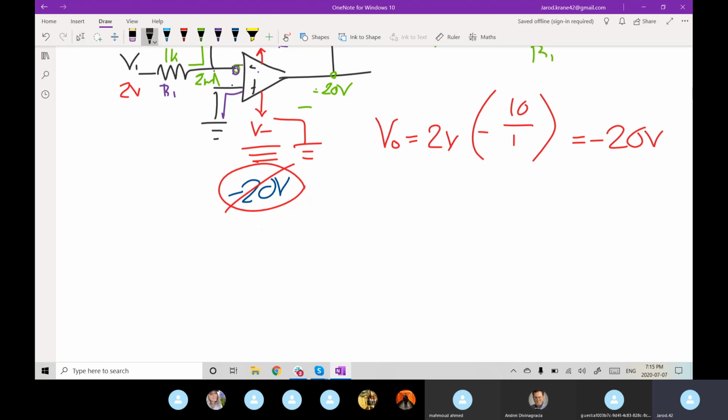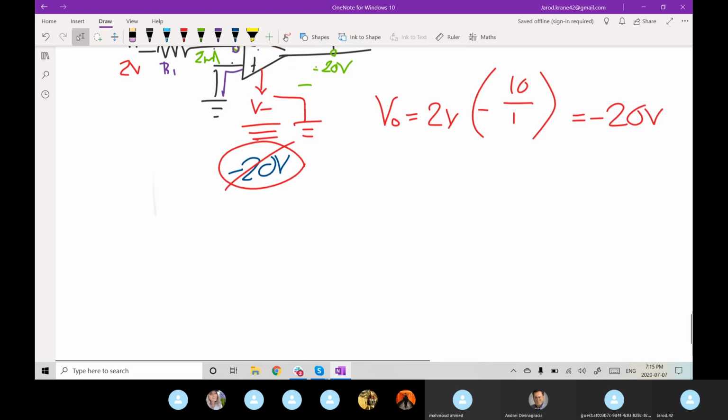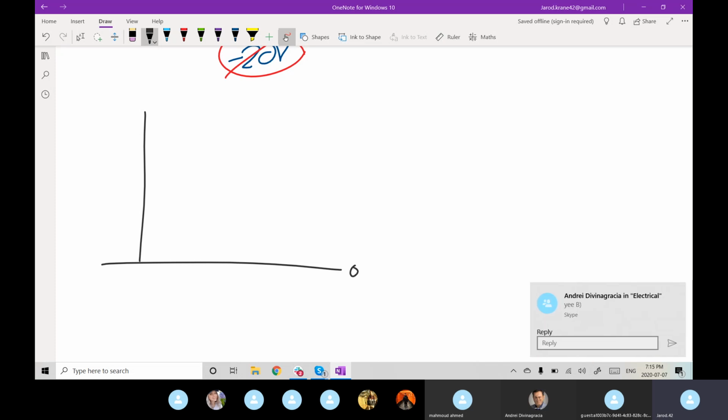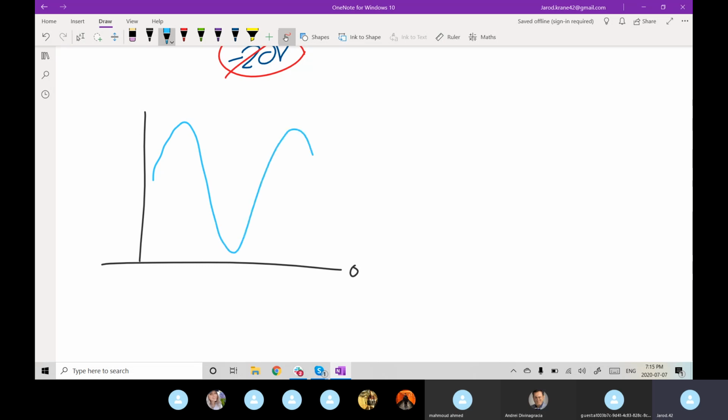So yeah, what we're wanting to do in this case is have it so our 0 point, and that our sine wave is now, instead of being about 0 volts, it's now about 10 volts. So that we're now able to send it plus minus 20 volts. So we get our 20 volt peak to peak signal that we want.